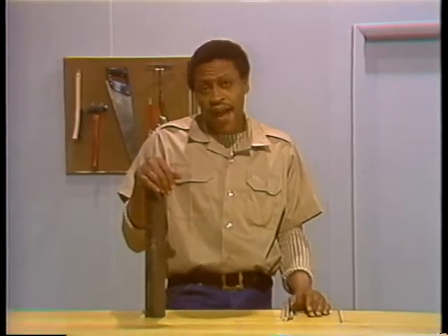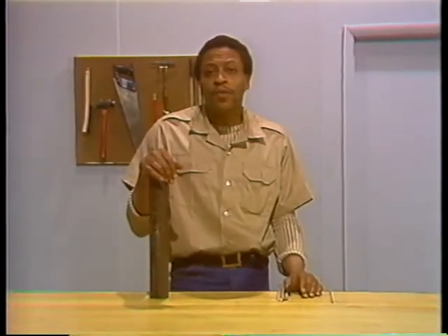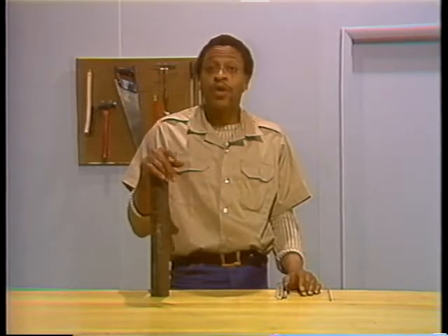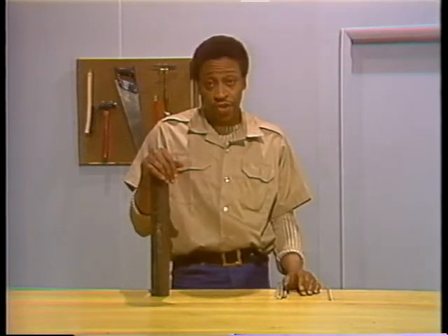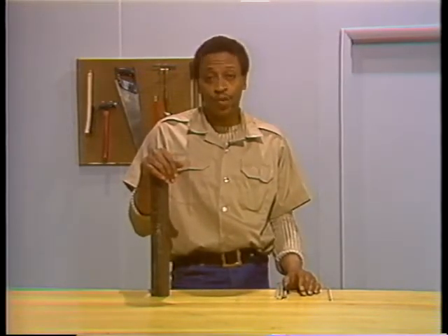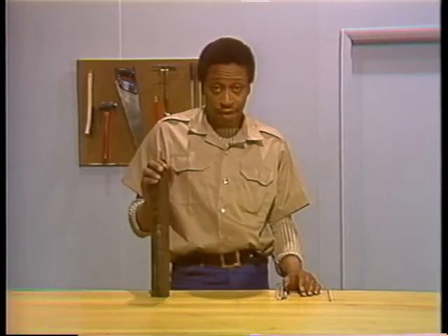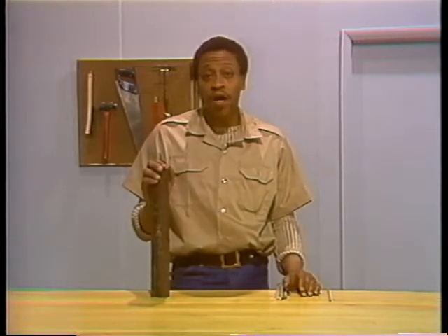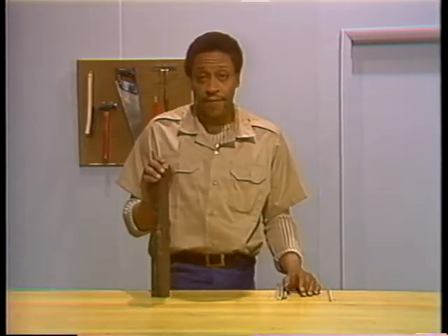The actual repairs you'll be involved with will be done inside a boiler, but in order to clearly demonstrate the procedures, we'll be working on individual boiler tubes in the shop. Each of the repair procedures we'll talk about will be demonstrated this way. The first method of tube repair is the replacement of a section of tube. Here, the length of tube containing a failure is cut out completely and replaced by a new section of tube.